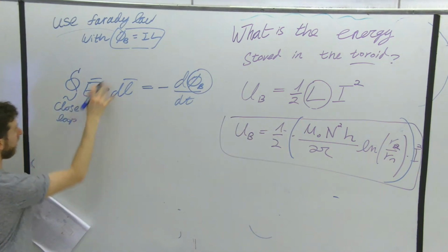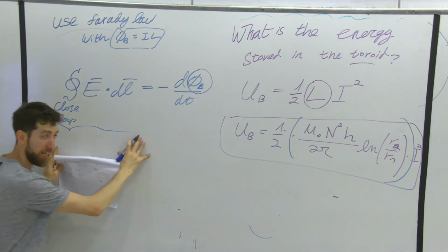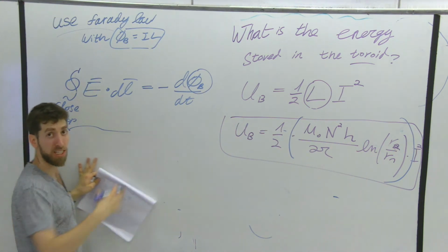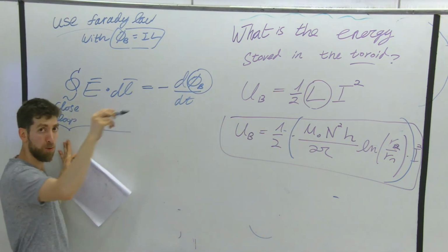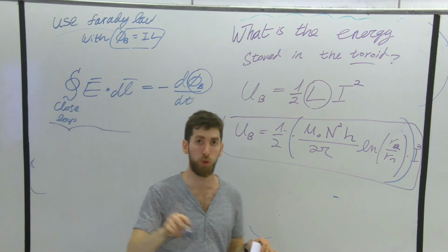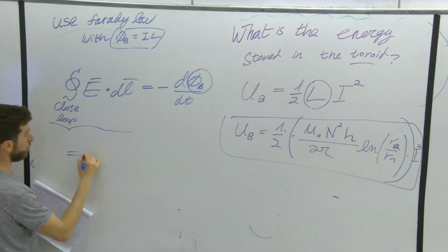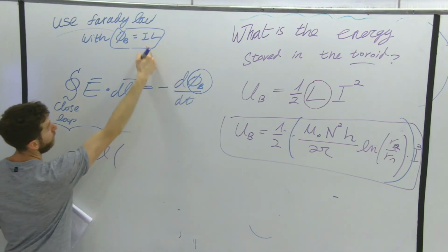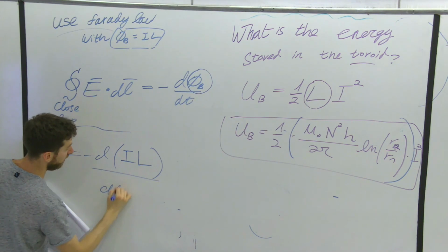Because this one can be many things, depending on your geometry. Probably in most of the cases, this is some electric circuit. Choose the loop of the electric circuit, as you saw in the RL question that we saw. And this term is actually equal to minus d, instead of Phi, I can put I L, divided by dt, right?